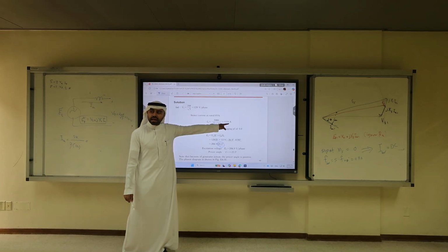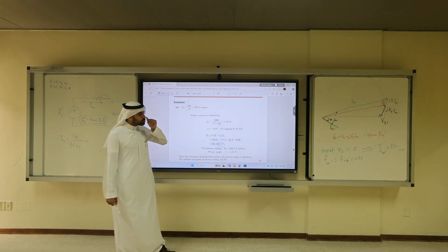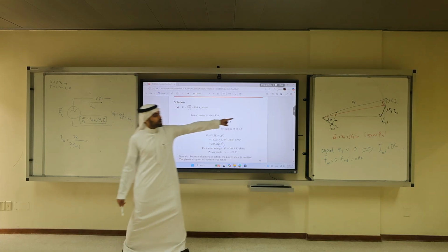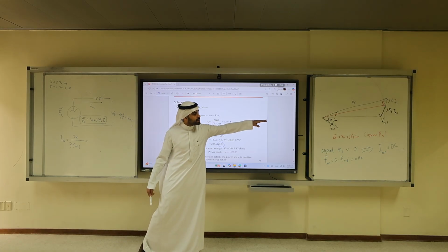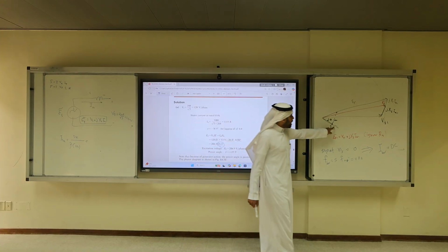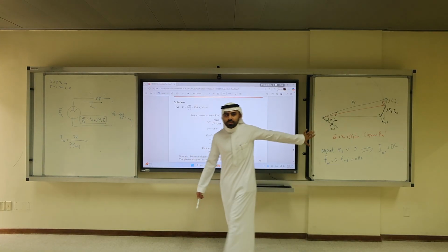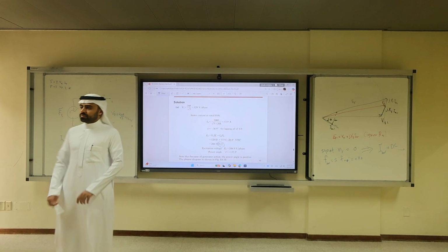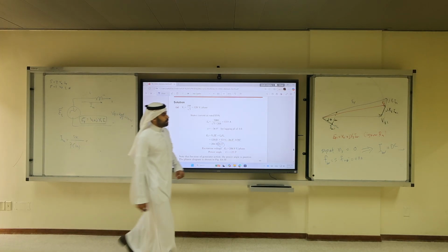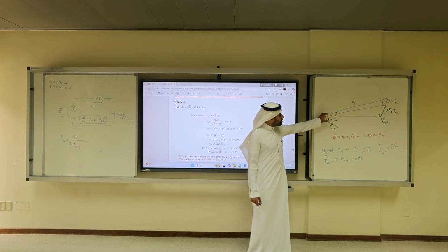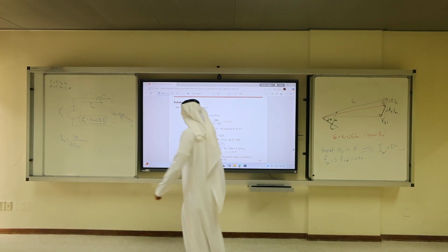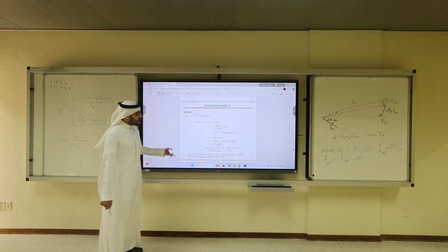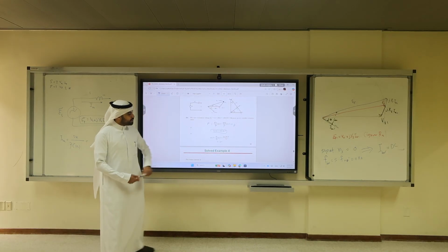So the current will increase. If you draw a similar argument to what I made here, to maintain Vt, EF is increased, IA will increase, and the torque angle will decrease. So the torque angle now is 21 degrees.